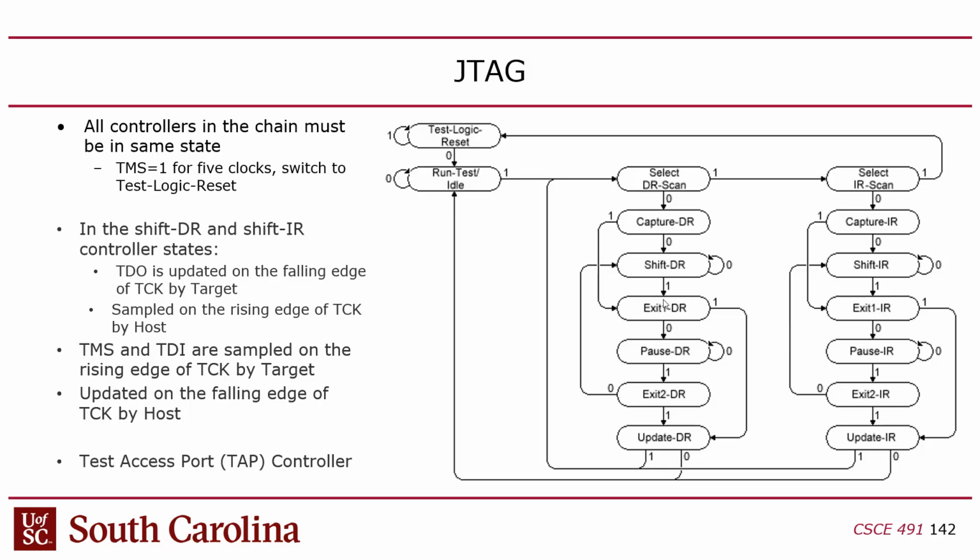Make sense? So the point is that JTAG has this state machine that's also fed by a serial bit stream, but because it's fanned out to all the devices, you basically set up all the devices on the chain using this, and then when you're ready to start transacting with them, it's just a giant shift register, right, through TDI, TDO.